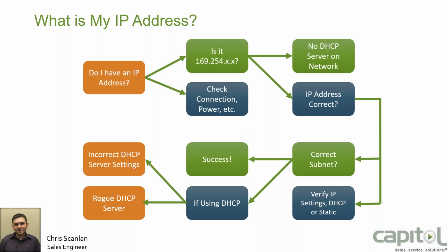I've seen where all of a sudden there is no RF filter on the outside of the house or the facility, and the neighbor has a MoCA signal as well. And next thing you know, you're picking up IP addresses. You're actually logged in. There's two networks over that one coax between the two houses. So just be careful, okay? The house issue may not be inside the house itself. So you really want to diagnose that signal.